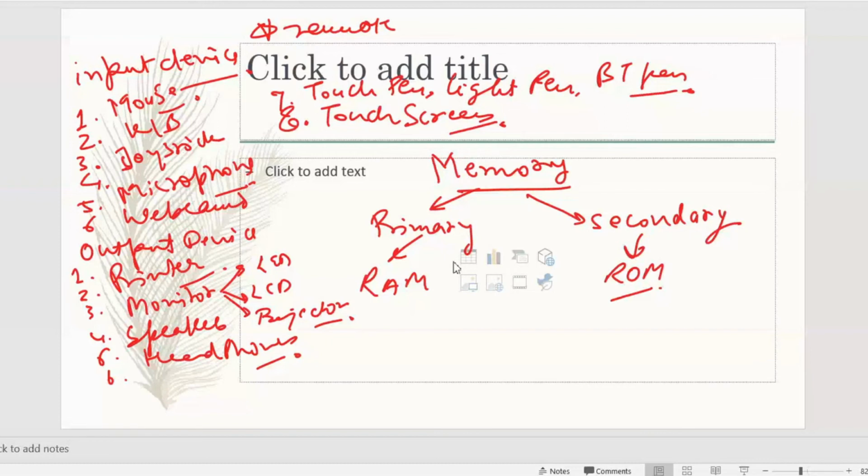The instruction set will be different for each and every processor. Once you change the processor, it's like a new book you are studying. They may not have the same instructions. No, there will not be any same instruction. There will be differences. All right. So a bus is a set of conductors intended to transmit data, address, and control signals to the different elements of the processor. Basically, buses are of three types: data bus, address bus, and control bus.